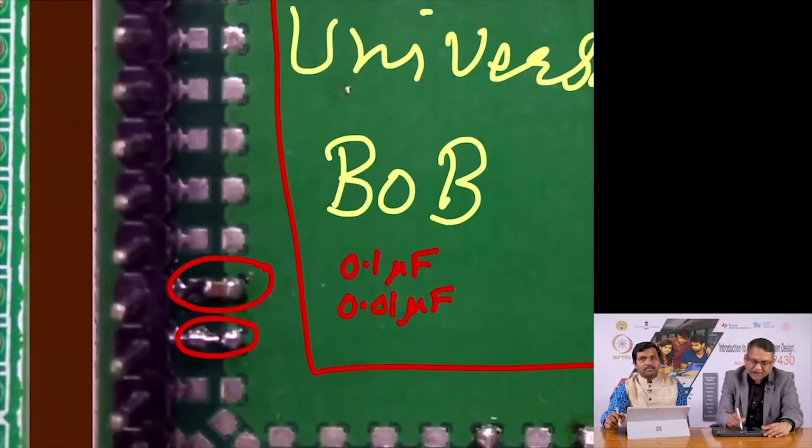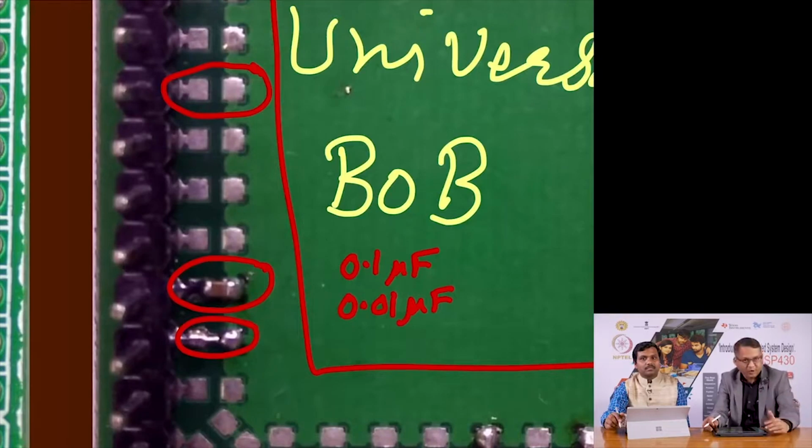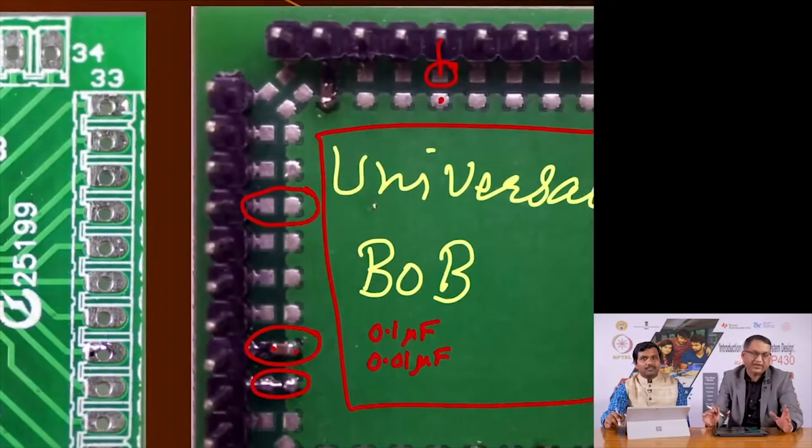So, what these pads serve the purpose of is either connecting a particular pin to the ground plane and therefore connecting all the ground pins together, or if that particular pin is a VCC supply pin, then it allows us to connect a capacitor between the supply pin and the ground pin. The rest of the pins, which are neither supply pins nor ground pins, are left unconnected, and these are the jumper pins which are soldered on the breakout board, so that this can be inserted in the 0 board.